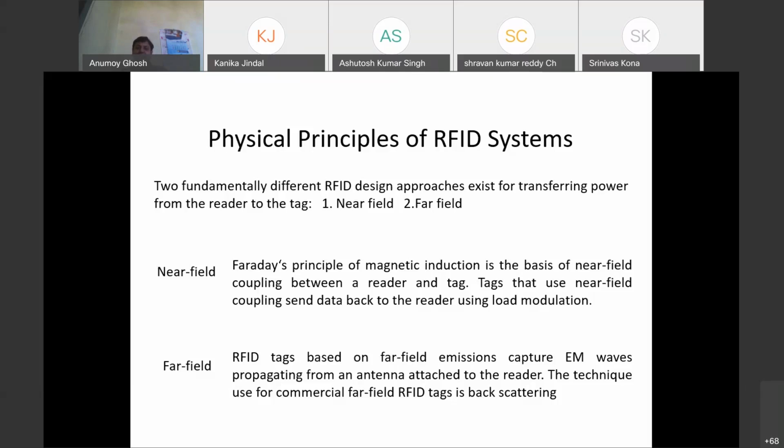From the antenna up to this x meter, the reactive part of the power will be dominant. That means the power will be either electrostatic or magnetostatic stored energy. It will be oscillating power. That zone is known as the near field. After we cross the near field margin, the power will be predominantly resistive, active power. That is known as the far field.